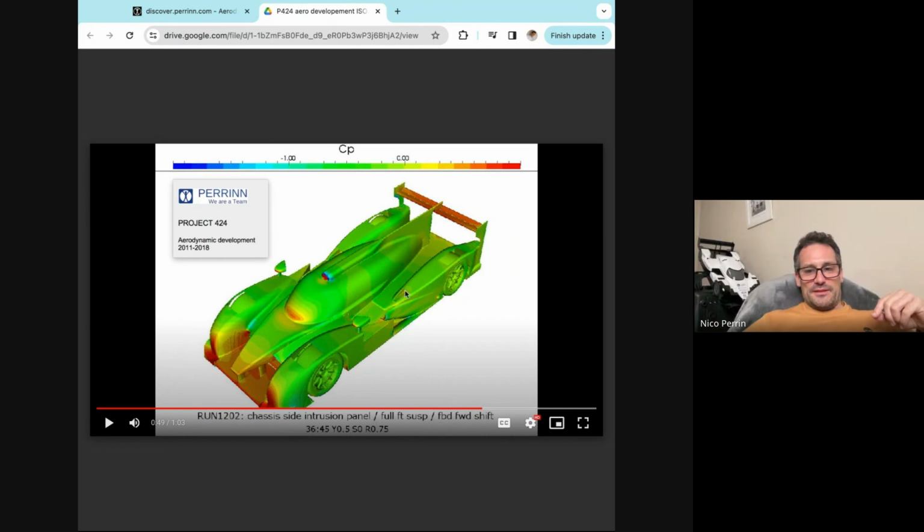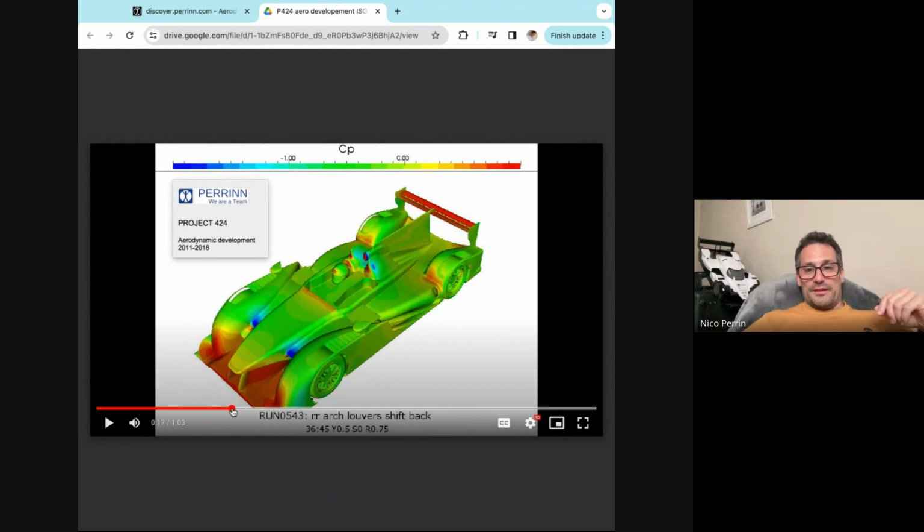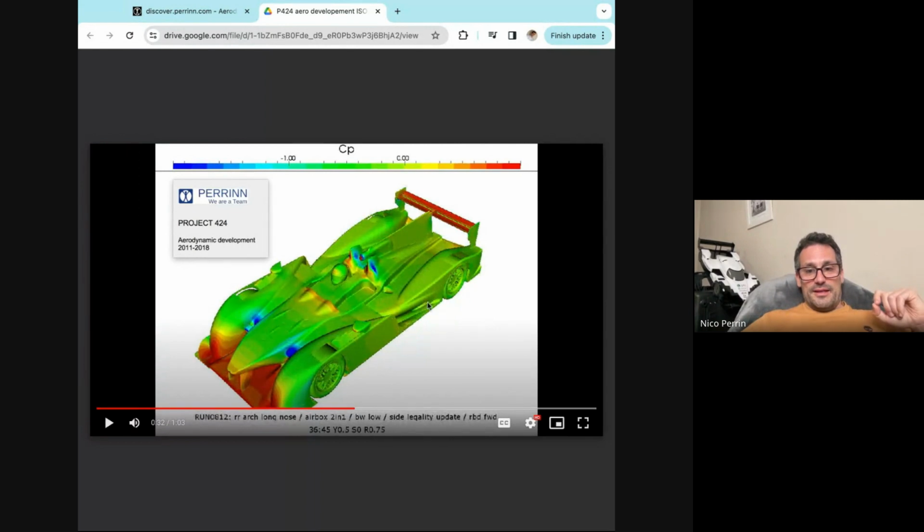I think because of this shape of side pods, reducing the top pressure and not feeding the air properly. But actually, if you look at the initial concept, it was worse. We had an intake here for the rear brakes. I overlooked some areas. The rear brake cooling was not good enough on this sort of brake inlet. When we did the Pescarolo car, the rear brakes were too hot. We didn't have enough cooling. You see the intake was there. That was not working very well.